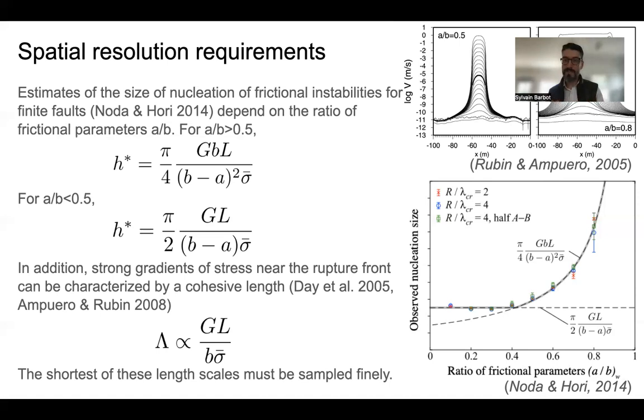So it is still a matter of testing to make sure that the model converges with finer and finer meshes. And currently, we don't have a universal recipe to predict the mesh size that would work without additional tests.